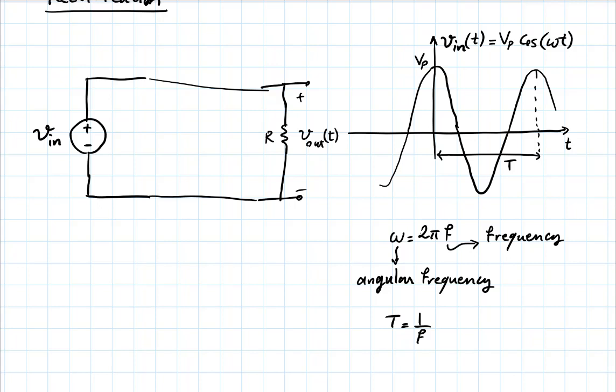This is where the diode came into play. And we briefly looked at a situation like this. There I put a diode in there. And I think we talked about it, for instance, in the case where I had a capacitor connected here instead of a resistor. And we'll soon see the effect of the capacitor in more detail. But think about this circuit for a moment, what this circuit does. So imagine this is an ideal diode, and plot V out as a function of time. Think about it for a couple of minutes on your own.